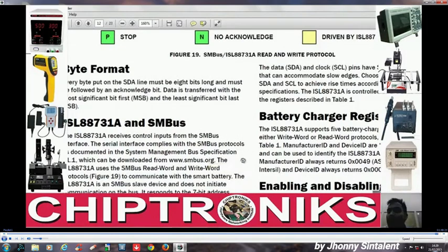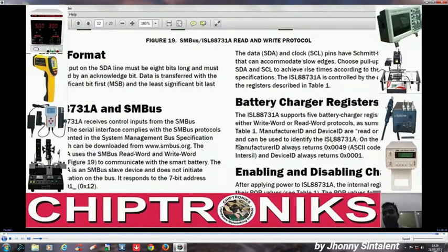and in that class I will describe the SM bus and how to sniff out that data, because now the charger ICs are getting more intelligent. They now have a direct SM bus connection from the IO IC, whereas in the previous version of the charger IC like Max 8725 they were hardwired. Okay, so I'll finish this class, and in the next class, just a small 30 minutes,